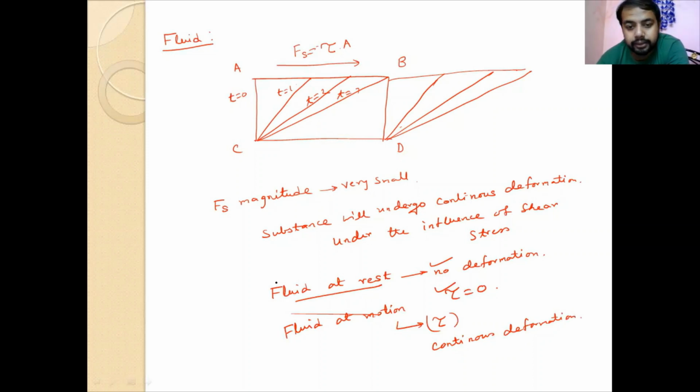So if the fluid is at rest, there is no shear stress, but there must be some normal stress, which we will come to when we discuss the properties. There is no shear stress, but obviously some stress would be there to establish equilibrium. This force is known as the normal stress.